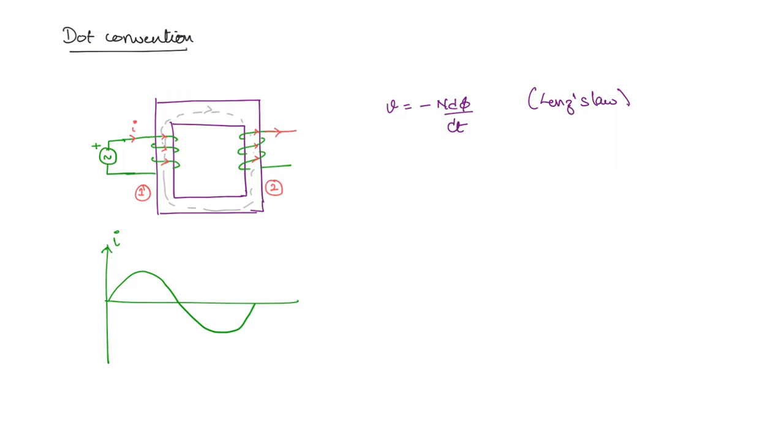Okay. So now this is the induced voltage. That means this coil is now driving the current. So the current is now coming out from which polarity it should come out from? For a source, it will come out from the positive polarity. So you're going to write the positive polarity here. Okay. So we have been able to find out the positive polarity, right?